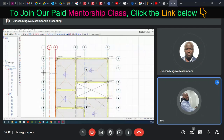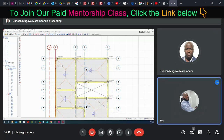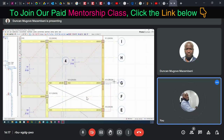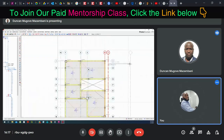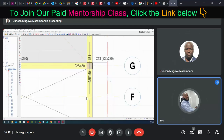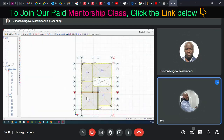Now escape. Do the same thing for the other one, for the left hand side. Click on that grid line, offset to that point. Click at the edge of that place, at the edge. That's fine. Now escape. We now begin to insert our slab. Go to the slab again.